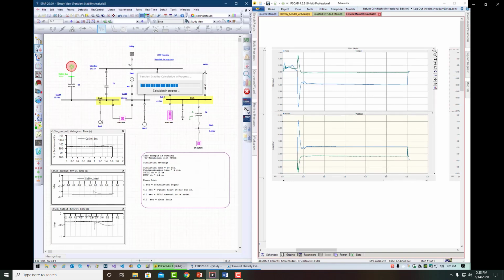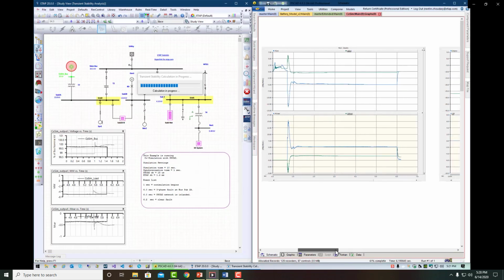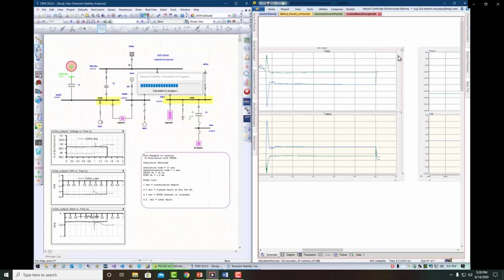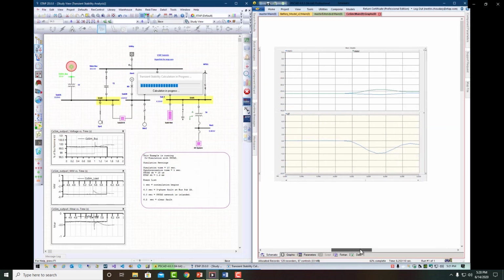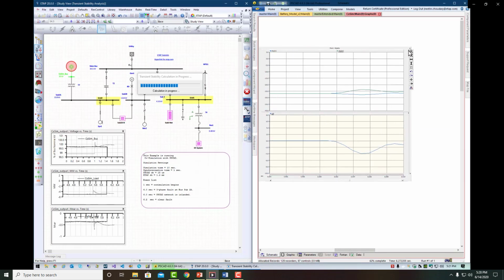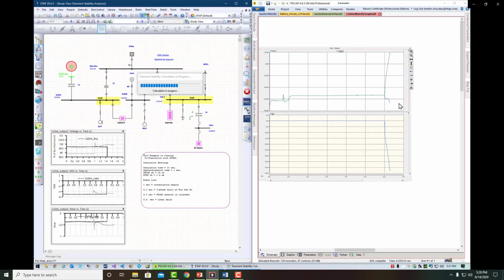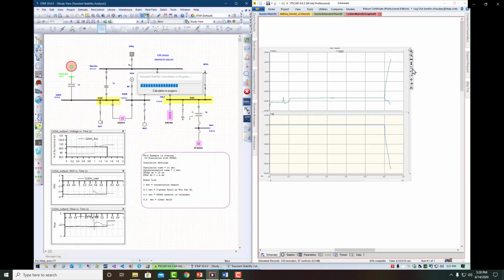As can be seen from the figures on the right side, before time equals 6, the voltage angles on both sides of the breaker are almost identical. However, after the two subsystems separate, the phase on both sides of the breaker diverge permanently. As a result, we cannot reconnect the two systems without a synchronization mechanism, which is not part of this case study.